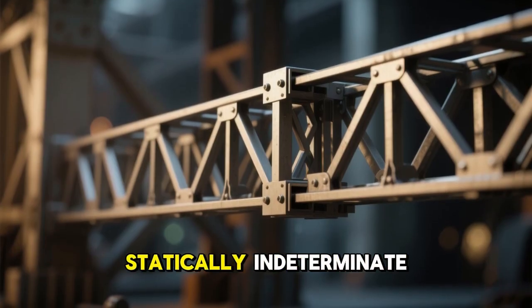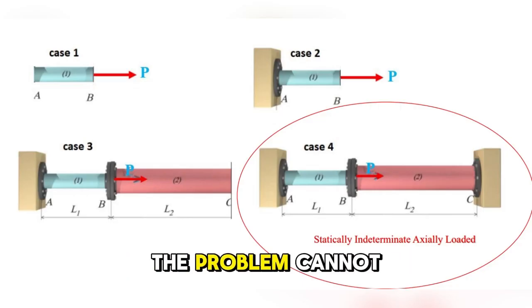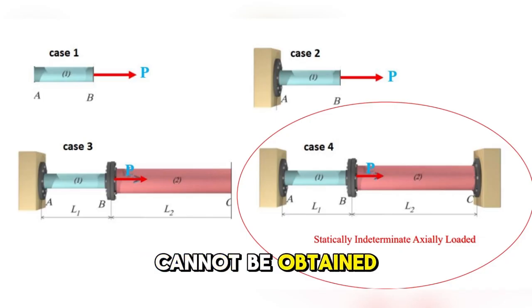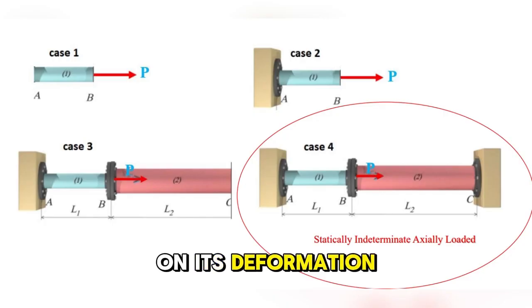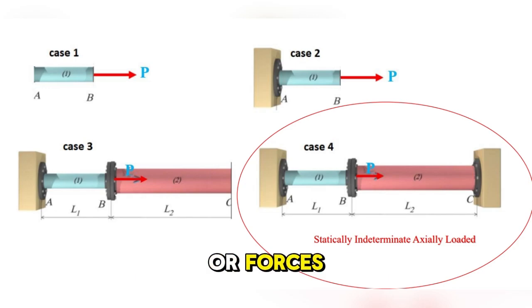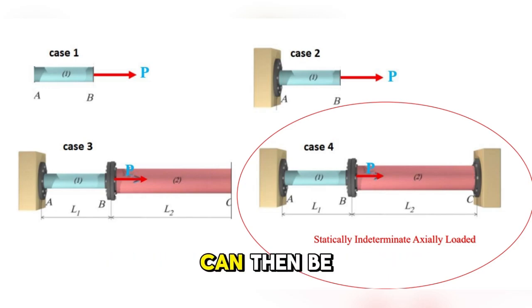Statically indeterminate, axially loaded member. Static indeterminacy does not imply that the problem cannot be solved. It simply means that the solution cannot be obtained from the equilibrium equations alone. A statically indeterminate problem always has geometric restrictions imposed on its deformation. We can, however, use Hooke's law to express the deformation measures in terms of stresses or forces. The equations of equilibrium and compatibility can then be solved for the unknown forces.